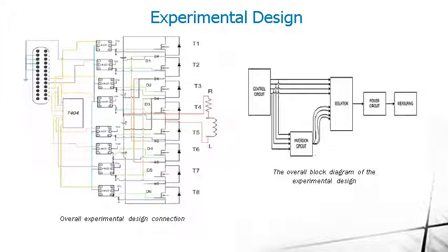and to prevent short circuit occurrence between the inverter switches. The power circuit that has been used is the single phase half bridge 5 level diode clamped inverter. It is constructed from 4 DC supplies, each of VDC equal 20 volt. 8 switches have been used in the circuit, and the switches are the IRF530 N channel power MOSFET. 6 clamping diodes have been used in this circuit, which are BY359/1500.